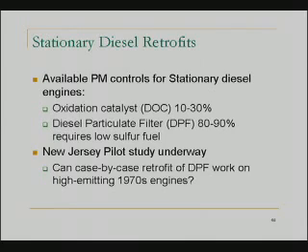Second category I want to talk about is stationary diesel retrofits. There are many retrofit programs for mobile source engines such as buses and trucks and the like. And essentially these engines are very similar to the engines that are used for stationary source applications. And the same types of devices would apply, such as diesel oxidation catalysts and diesel particulate filters.